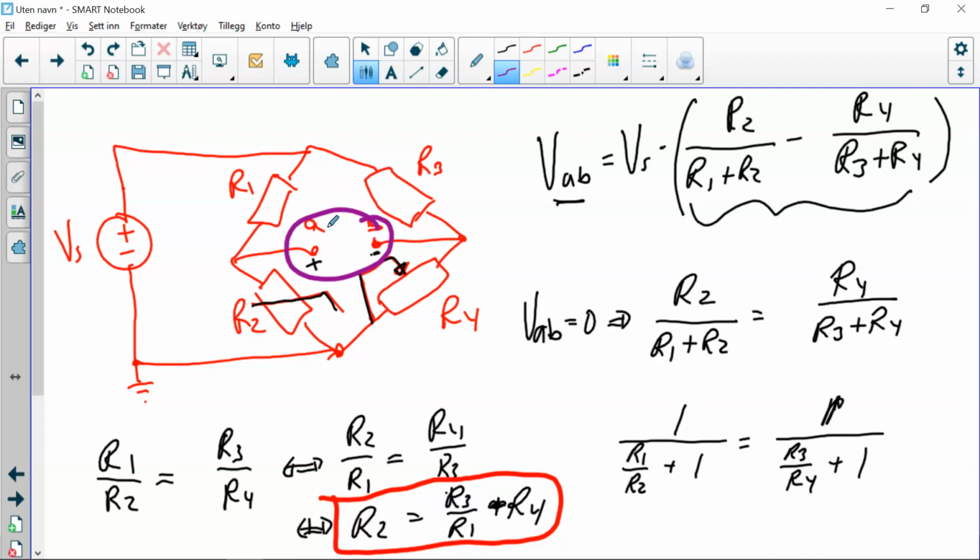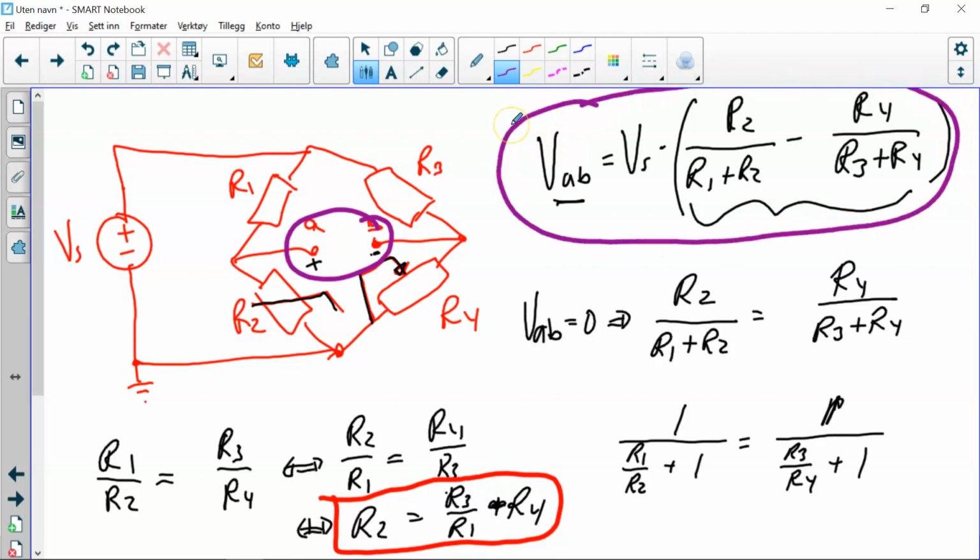However, as long as we have computers, I can take this equation and solve it with respect to the unknown resistance. And if I do that, I can put that into a calculator or a microcontroller and use the measured voltage to calculate the unknown.